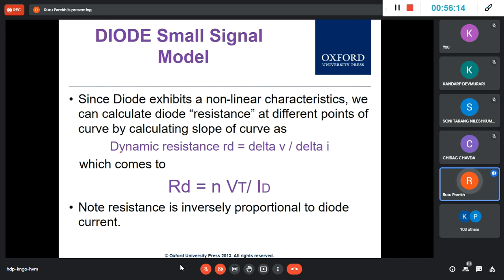So now you know that the diode curve is exponential, it is not linear. And as I said, in the piecewise linear model, RD will remain same, but in the real curve, exponential one, your RD is changing, and hence we say it is a dynamic resistance. And it changes as per the voltage because, as you can understand now, you can visualize.